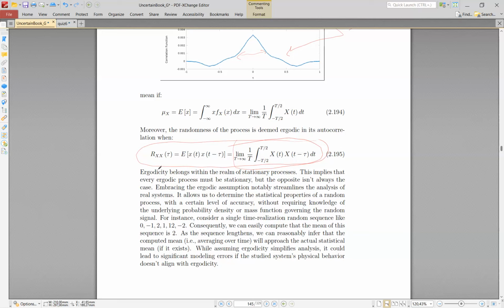Always remember this way of finding the autocorrelation. However, we are always using it. In wireless communication, we mostly assume that the signal is ergodic. This assumption of ergodicity is valid when we talk about very short symbol transmission. If the symbol duration is much lower than the coherence time of the channel, it is valid to say that it is an ergodic process anyhow.